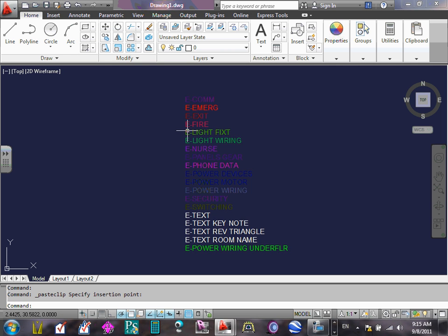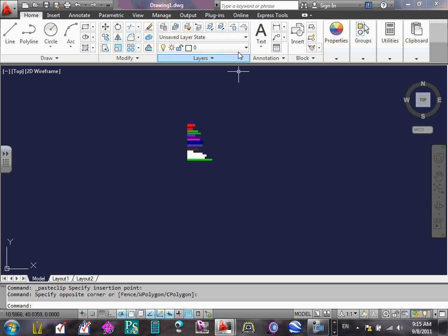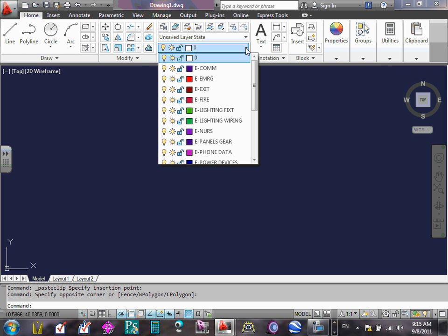So what I did, guys, I copied these layers. By copying them, Chris, you actually just put them in your drawing right here. By copying them into the new drawing that you created, you basically created these layers with their colors. That's the easiest way. It's already created for you. I'll show you how to edit them in a second.